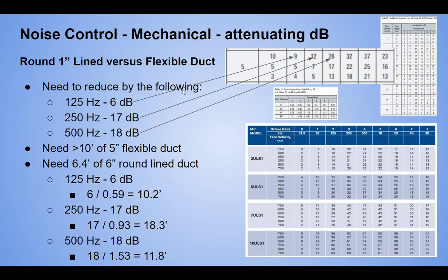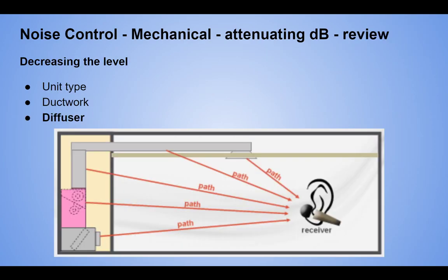So we're looking at what we're saving on this aspect at the 6, 17, 18 dB. At 250, we're down at 24, 21, and 14. That covers these easily. We wouldn't need to do any of these. That would be overkill. And really, in all actuality, the silencer is a little bit of overkill, but it'd be better on there. If we're just looking at that case, that would bring that down. We'd solve that problem.